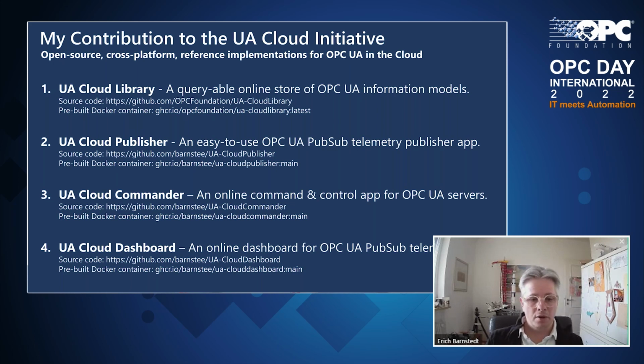UA Cloud Commander also runs on the edge, and it talks to the MQTT broker, obviously subscribes to predefined topics that you then send messages to execute commands like read an OPC UA node, or write an OPC UA node, or call a method node on an OPC UA server.